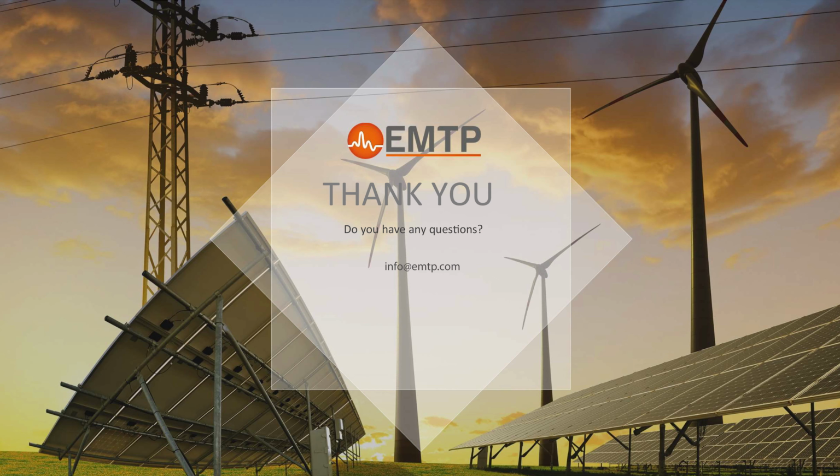Yes, so during the start of this project, it was 2 years back. In the literature, the most common gains that were creating some sort of problem for PV were either the PLL gain or the PI controller gain. With that knowledge, we did some sensitivity. At first, we actually did manual tuning before PSO. While doing the sensitivity, we found that these 3 parameters were changing the response a lot. So first it was manual tuning, manual sensitivity analysis, and from there we chose these values.